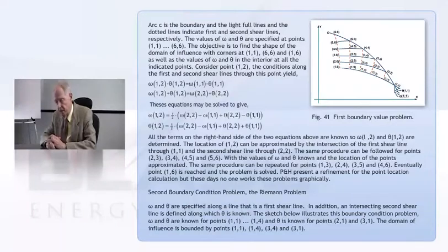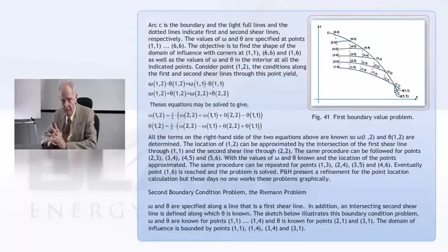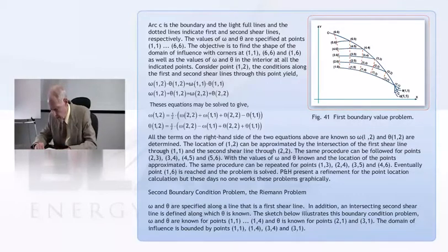So on the next slide, there's a sketch where the heavy line is the line on which omega and theta are known. And the Hencky equations, the equations for the Hencky theorem, are given on the page. And as you can see, you can go along that line. You could start, if you really felt like it, on the points 1, 1, and 2, 2.